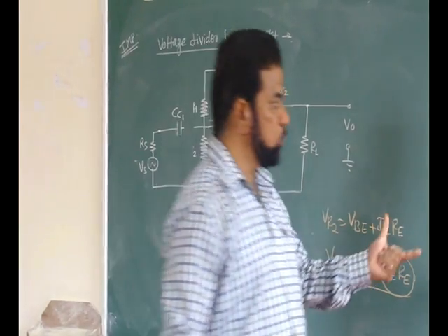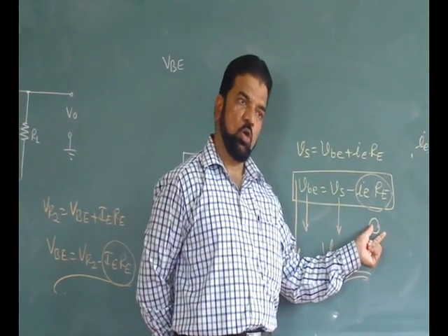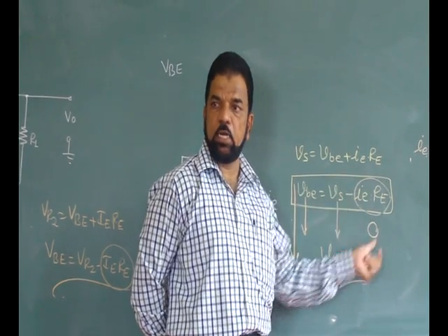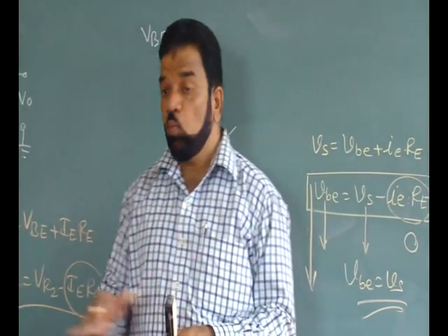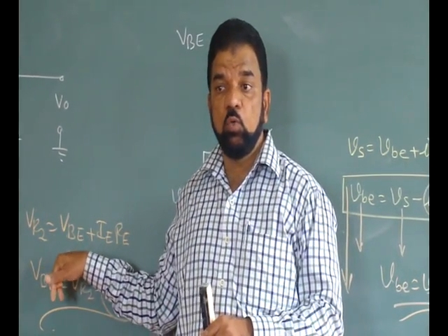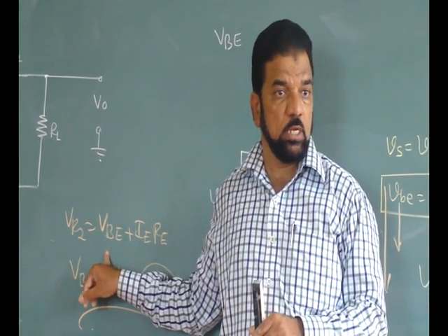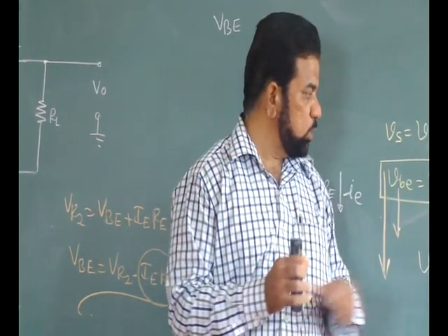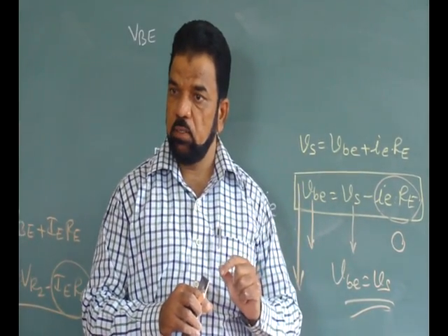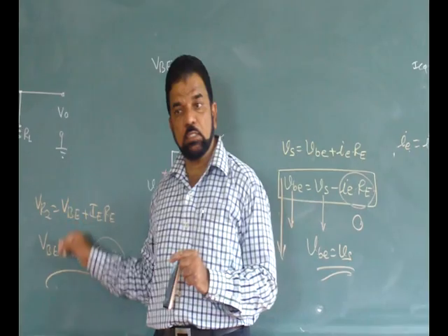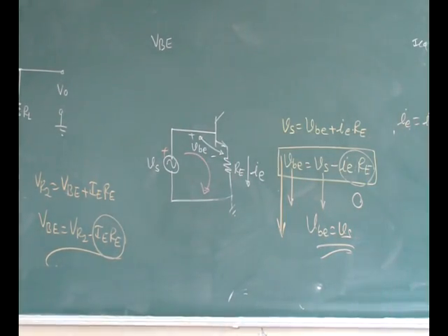Okay. So if your answer is just, sir, make this equal to 0, all right, you can get the negative feedback equal to 0. There is no negative feedback. But at the same time, whatever advantage we got, you are losing the advantage. Understand the point? To have this term equal to 0, if I just straightaway remove the RE, that means I am not getting the stabilization. So I have to think in a different way.